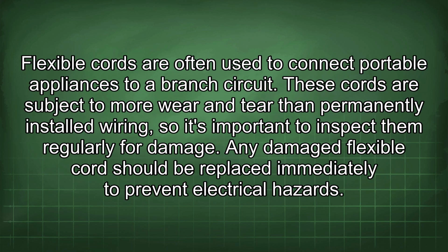Flexible cords are often used to connect portable appliances to a branch circuit. These cords are subject to more wear and tear than permanently installed wiring, so it's important to inspect them regularly for damage. Any damaged flexible cord should be replaced immediately to prevent electrical hazards.